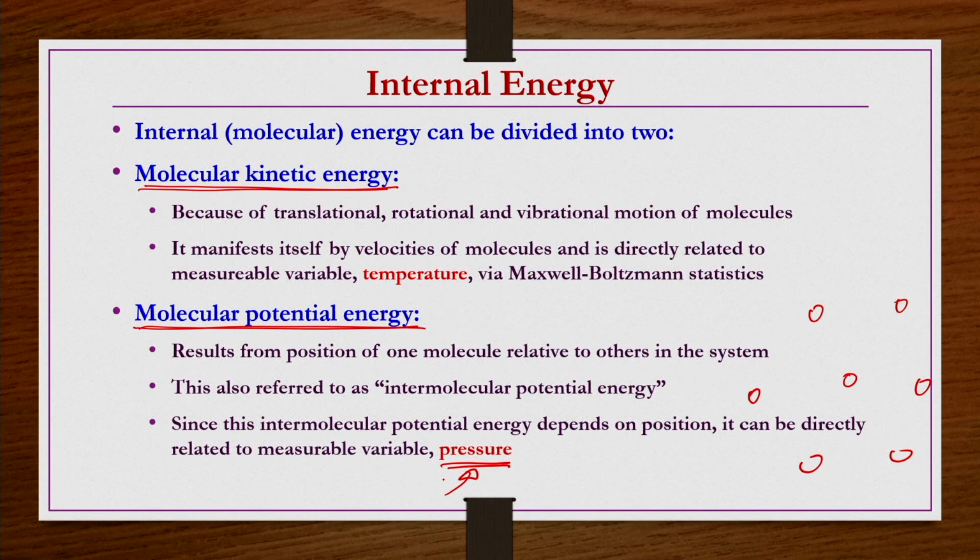We now understand that the non-ideality in the system is because of the intermolecular potentials, that is, intermolecular forces, and these are directly related to the pressure of the system. That is the reason the generalized expressions for the fugacity coefficient or fugacity of pure component i, which we derived in the previous lecture, were derived at constant temperature and composition.